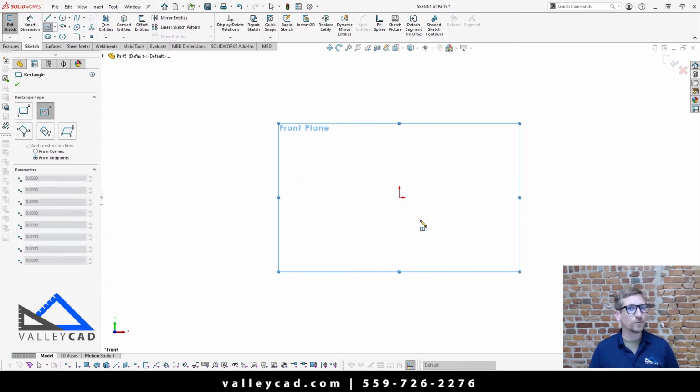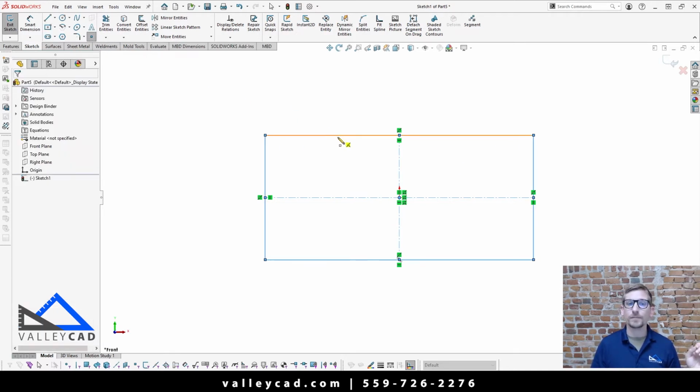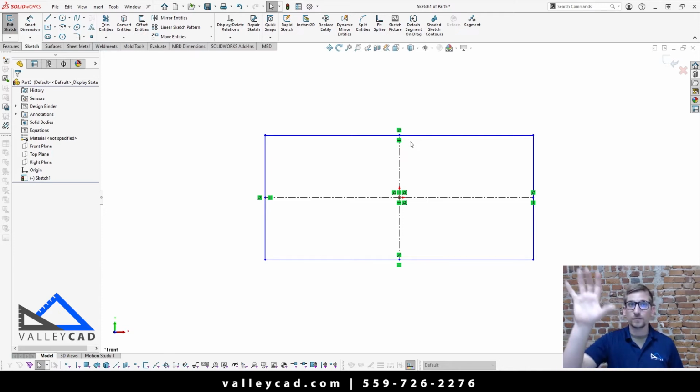Okay. Here's a reason why, as I'm sketching this out for you. When you are working with weldment profiles, remember how you can come in and locate your profile based off of your path? Well, what it's utilizing are endpoints of entities, and each of these lines are considered an entity, or actual sketch points that might be on an entity. So in this scenario, I generally make all my rectangles with midpoint construction lines as compared to the diagonal or from-corner style, mainly because now I have extra grab points here that I can locate this profile about my path. So that's why I do that there.